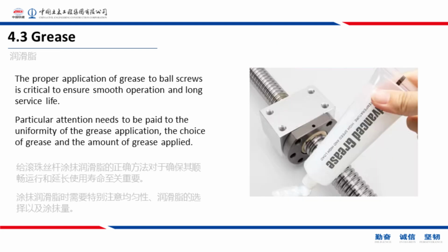PPT 41. 4.3 Grease. The proper application of grease to ball screws is critical to ensure smooth operation and long service life. Particular attention needs to be paid to the uniformity of the grease application, the choice of grease and the amount of grease applied.